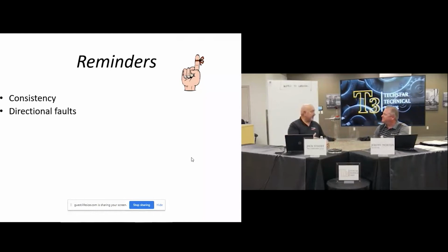They did it at night, and the night crew didn't anchor the bolts down for the fan. So you had a vertical. You could actually go over there and spin it with your hand. In vertical, it showed up, and I said, let's tighten this down. Once they tightened it down, all the levels were around 0.15 or less.